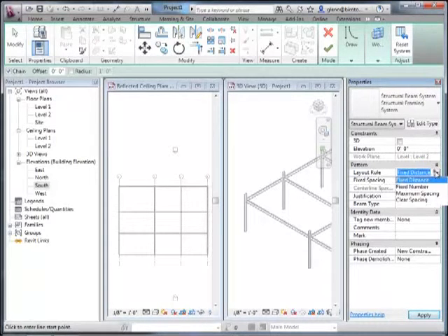The other rules would let you say that, no, I want to have 5 beams between here and here, and whatever that spacing is, it can be whatever it is. But I'll stick with fixed distance because that's probably the most common thing. Whatever the spacing is going to be, if it's a simple wood frame structure, they could be, if it's just very lightweight joists, every 16 inches or every 24 inches. If it's steel, maybe it's every 3 or 4 feet, whatever it is that your intermediate joists are going to be.